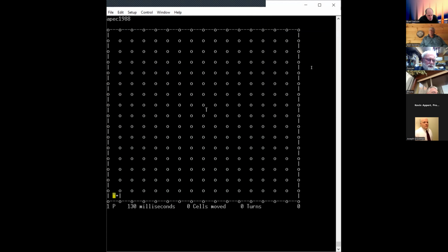Okay, so this is running on mouse hardware. I've got a little processor board that I use for this kind of thing. It's the real processor board that's used in the real mouse. So the same code is used both for simulation and the real mouse. I only wrote the code once. So any limitations of the hardware become apparent during development. If you're doing your simulation on a PC in Forth or a different language and not actually running it on the real hardware, you can really mess yourself up. You can convince yourself that your software is fast enough when it's nowhere near fast enough.